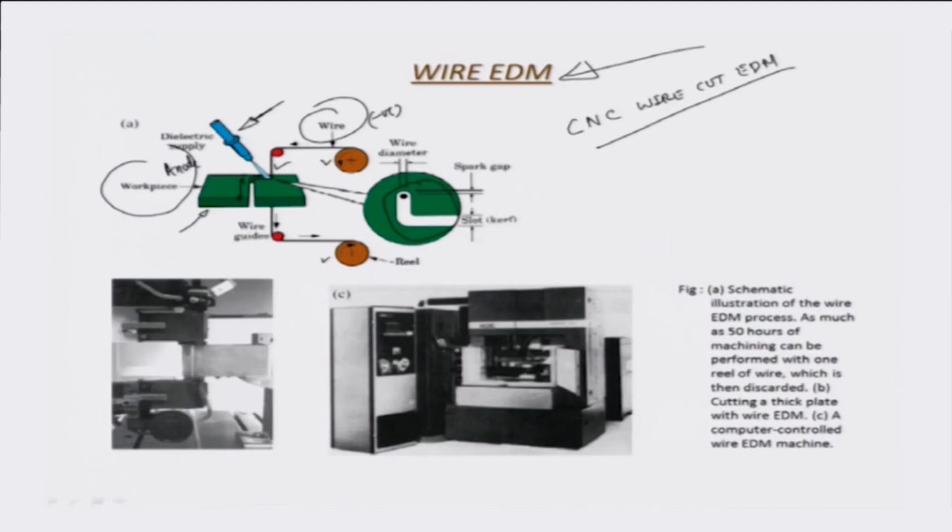So the motion of the wire path would be first in this direction and then in this direction. So the wire comes all the way into this and then goes like this, and wherever the wire proceeds, there is arcing because of which this complex L slot, depending on the path or the guide of the wire, would formulate on the workpiece.